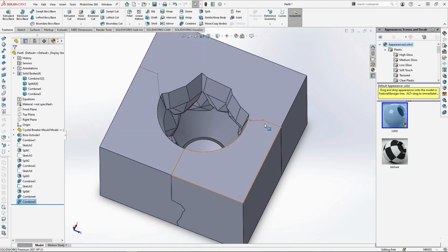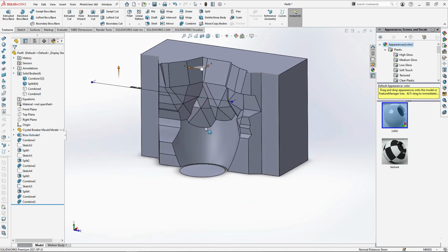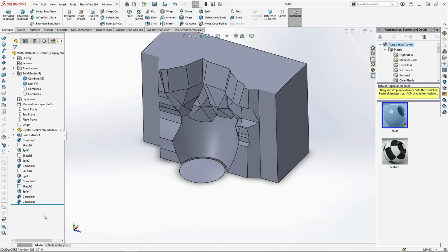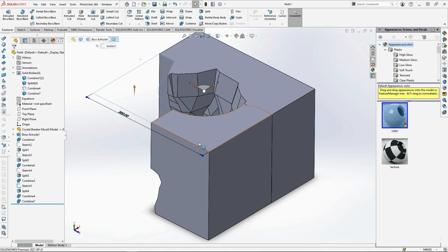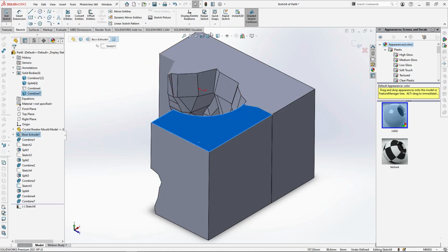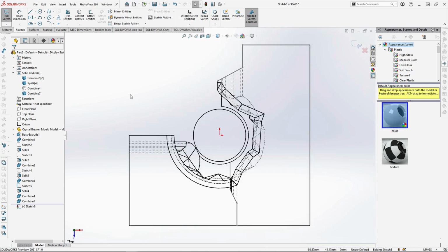When we re-hide the smaller mould parts, you can see the flat surfaces created. This also creates neat mould split lines from the outside. I now need to do this for the other mould parts. So hiding this part, start a new sketch onto this face. View from the top and turn on wire view.